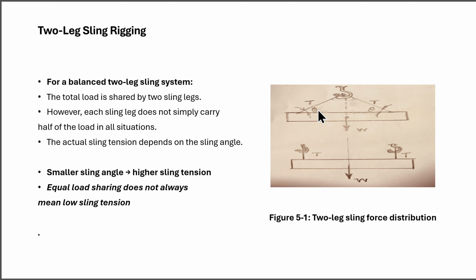Here is the sling angle, here is theta. Smaller theta, smaller sling angle, higher tension. Load sharing does not always mean lower sling tension.